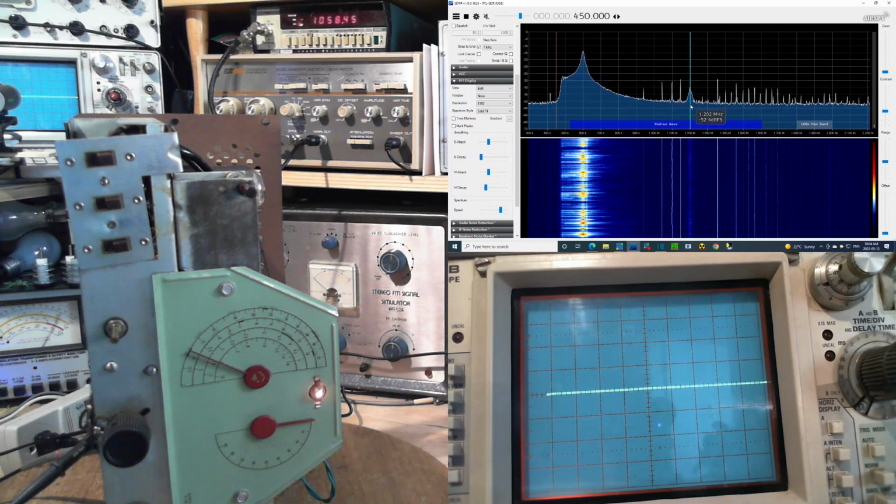What if there was a very strong signal there? The other thing is, with the local oscillator off, there's nothing coming out of the IF. You can see on the oscilloscope, nothing at all. That means the AVC is allowing the radio to operate at its highest sensitivity. That makes all these things kind of obvious on the screen here.